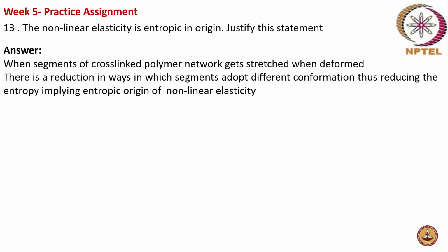Internal energy is getting converted to elastic strain energy that is being stored, and when it returns to the original position, it is released. So that is of enthalpic origin. That means in non-linear elasticity, the entropy term plays a critical role since there is a reduction in possible conformations, whereas linear elasticity becomes more of an enthalpic spring.